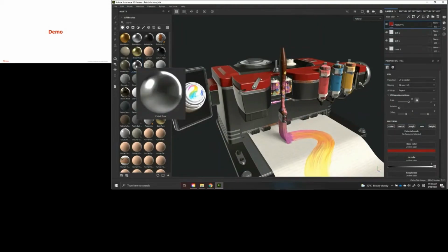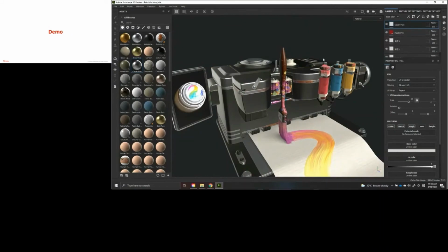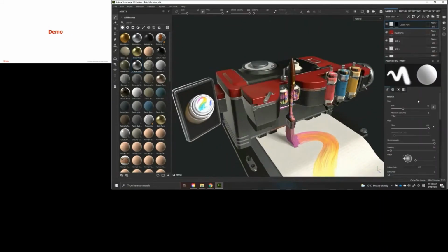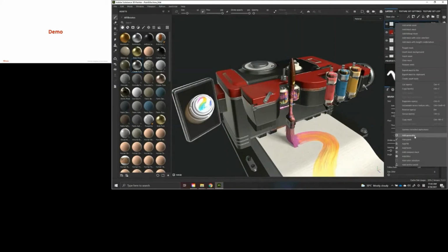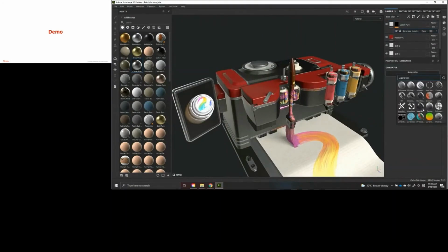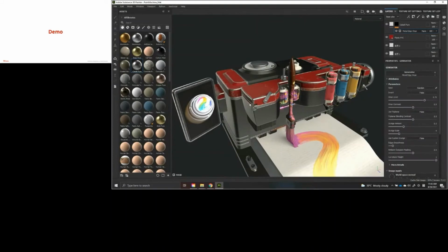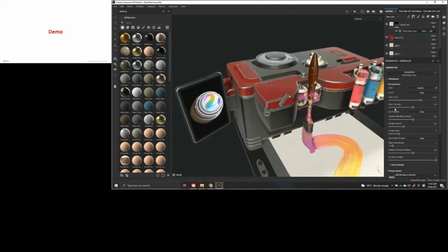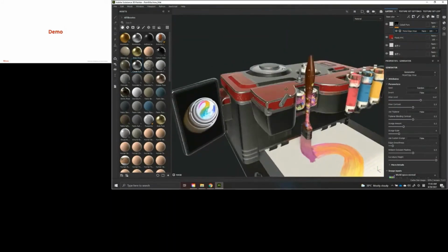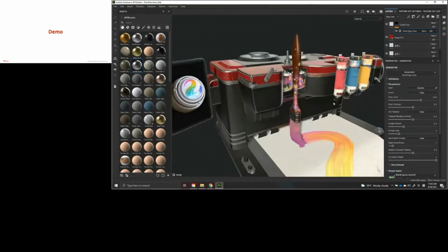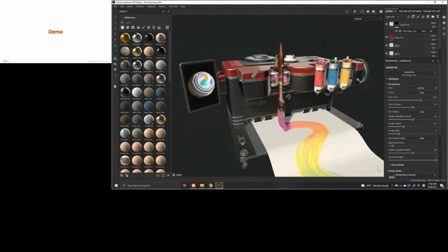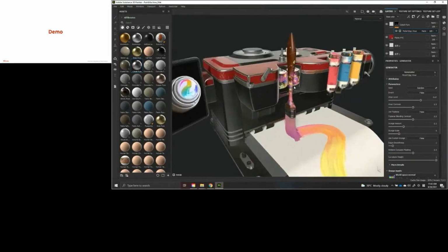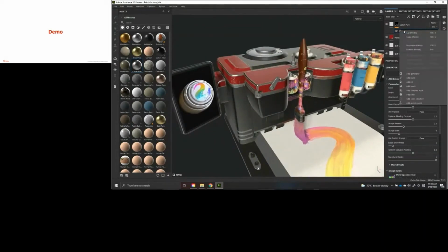I give it new materials, create a black mask, and use some automatic filters already inside to create some weathering, a metal edge wear. I can also change the different levels, and of course use brushes to paint and remove some parts I really don't want. So this is a very quick way to use Substance 3D Painter.